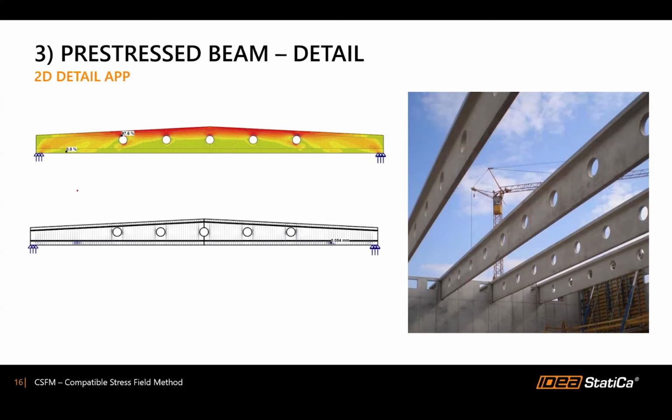If you put in the openings, there will be a decrease of the stiffnesses, because the section is affected by the openings. There is a reduction of the material, so the stresses will change. Because of the opening, there will also be some concentration of the stresses, which you need to handle somehow. If you use 1D elements or beam elements, it's not possible to capture it. And I will show you the power of this link between our two applications, this interoperability.